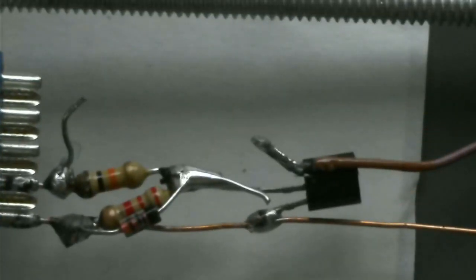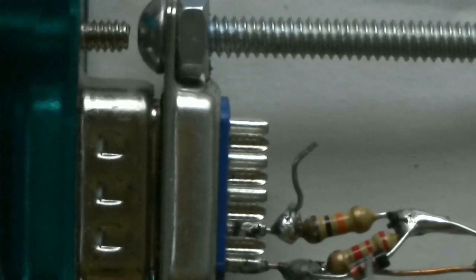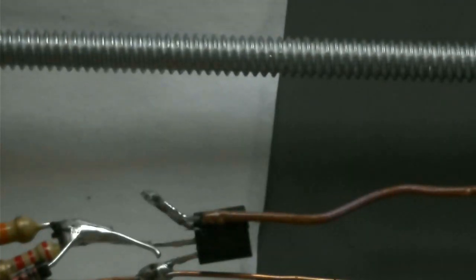I have a couple of bias resistors, and a diode in there to help with any spikes. That might be a little bit of overkill, but at any rate, this is what I did. The voltage coming off the computer port, which is the 7-8 volts, is reduced for the biasing of the transistor, and then the emitter of the transistor is hooked to ground, and the collector is what makes the pin that would have been on the repeater go to active low.